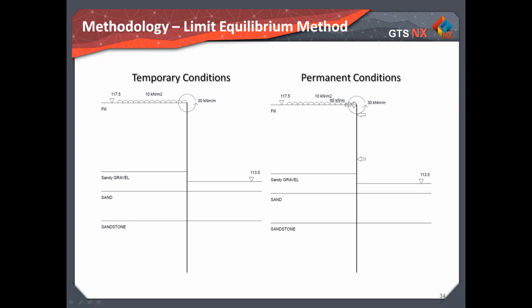The analysis results are then automatically tabulated for each construction stage in terms of the wall's shear force, bending moment, and deflection, as well as the factor of safety at given depths of the wall. The structural details of the piles can also be determined in terms of main and shear reinforcements. In either case, as you can see, the limit equilibrium method only considers half section of the problem, which is a function of the method.